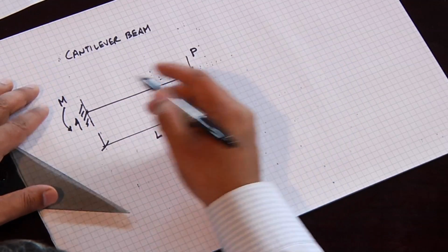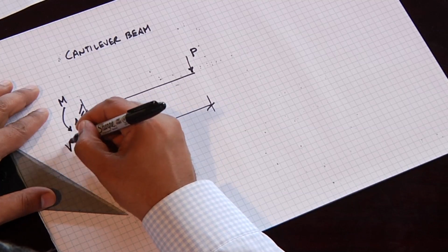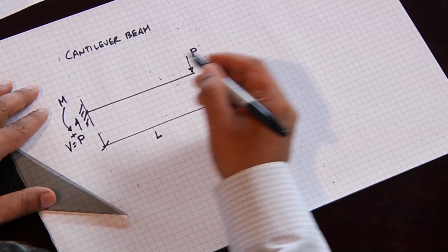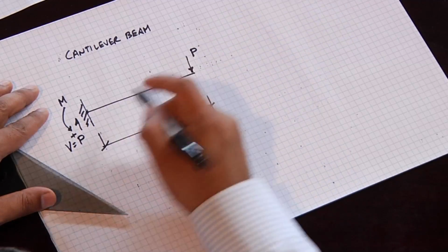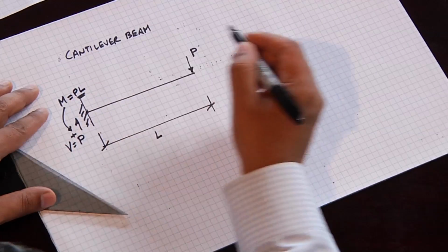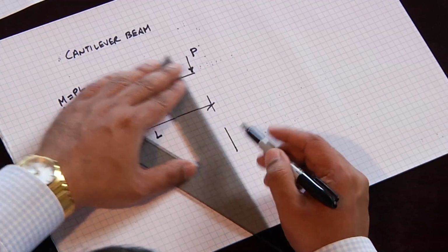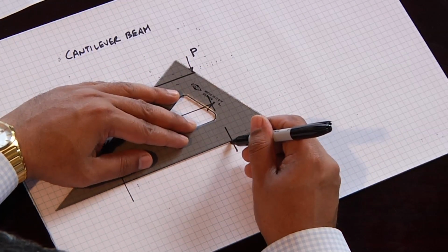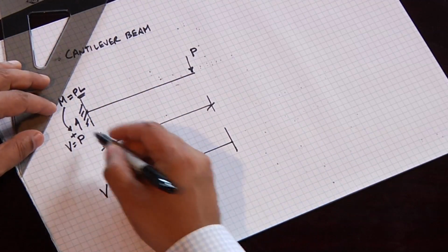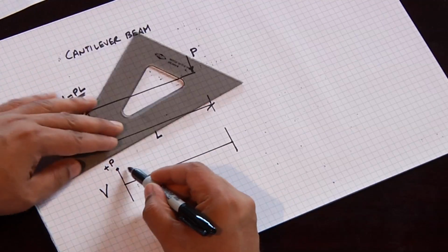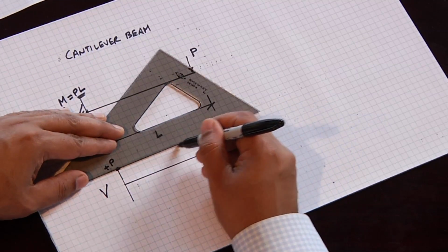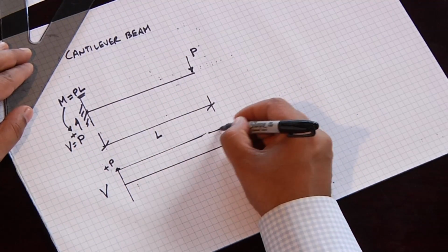And so right away, we already know that the end shear here is going to equal P, because this P is going down, and the moment, which we'll talk about in the next segment, is actually equal to P times L, but we'll talk about this separately. The shear diagram for this is really quite simple. If we do a free body diagram, we graph the shear. We're going to start off here at plus P. It remains constant because there's nothing else going on inside the beam. There's no other load, and then it drops down to 0. And that's our shear diagram.